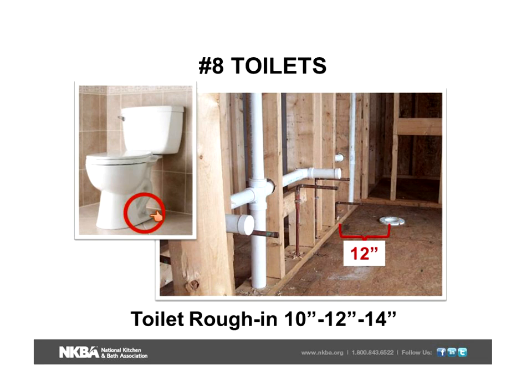You failed to measure the client's existing toilet. To measure the client's existing toilet, I'm going to measure from the hold-down bolt, which is what comes out of the center of the closet flange, to the back wall. Now, this is a finished back wall, so you know it's going to be less than 10 if it's a 10-inch, less than 12 if it's a 12-inch, and less than 14. But it's not going to be less a great deal.